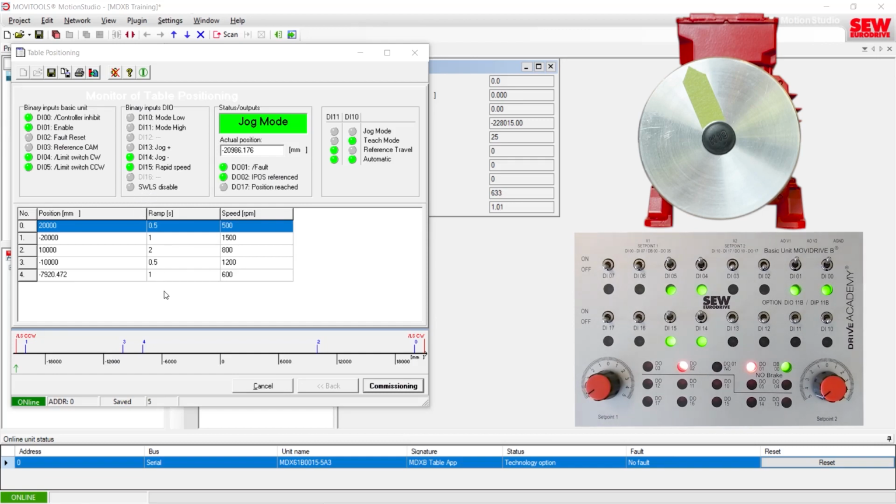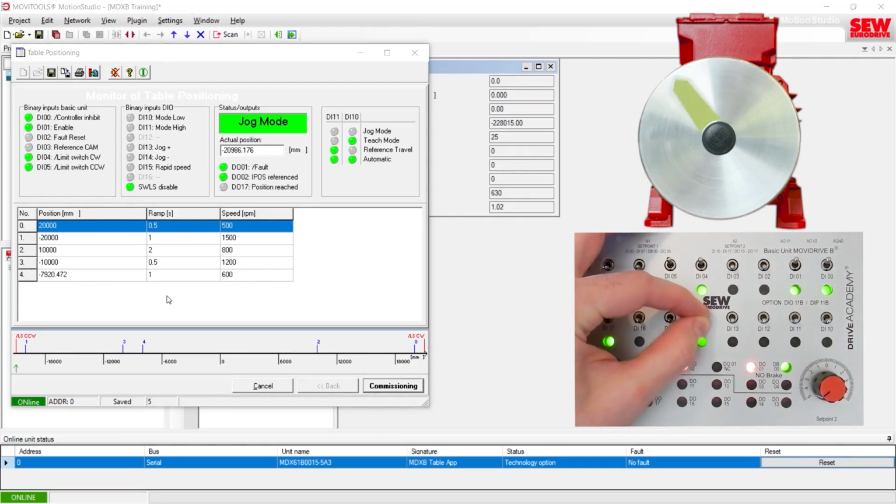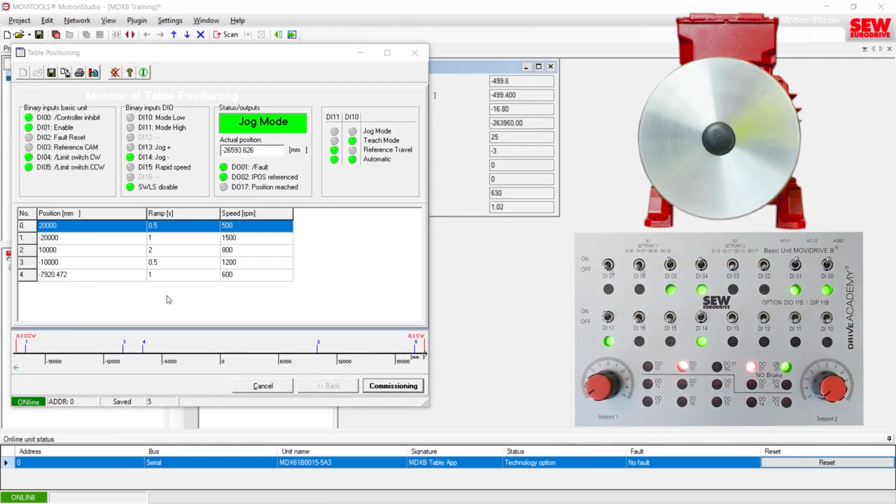First, we can turn off the jog minus input so the motor doesn't move. Then we can activate input 17. And then now we should be able to over travel past our software limit switches. So let's try jog minus again and see if we can keep going further. And then we'll deactivate the fast speed as well so it's not going so fast. All right, and then now it lets us travel past the software limit switch.